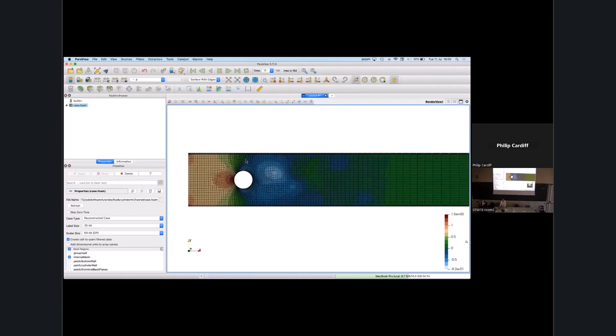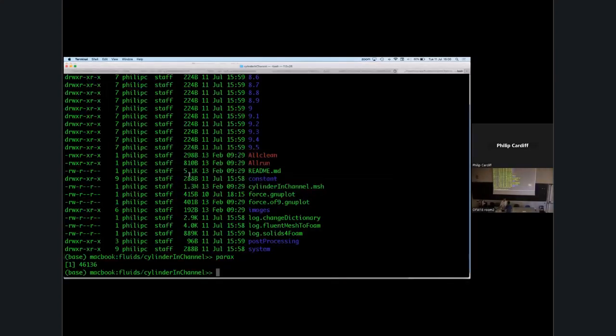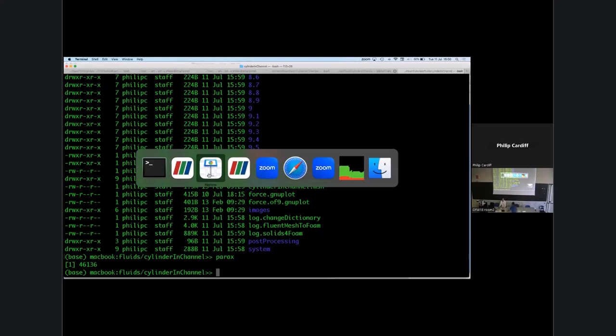So you can run this with pimpleFoam and check the answers are okay. It's curious as well because the port, yeah, thanks, sorry about that. If you run the 3 different versions supported, there are 3 different ports of pimpleFoam. Actually, the foam-extend 4.1 version of pimpleFoam is a little bit less stable for some reason, but you get slightly different answers with each of them.